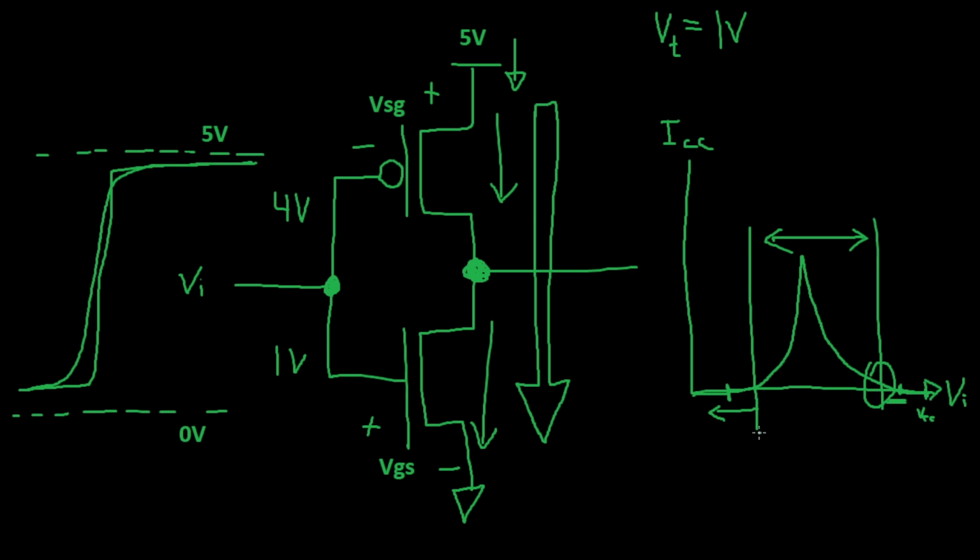So between 1.5 volts and 3.5 volts, the input is in an unknown state. And you really want to switch through this very quickly. That's why you have that input transition rate. Looking at it from the waveform, we would have our VIH somewhere around here, so we need to be above that value in the high state, and our VIL below here, and we would need to be below this in the low state. This is where we're transitioning very quickly between low and high.